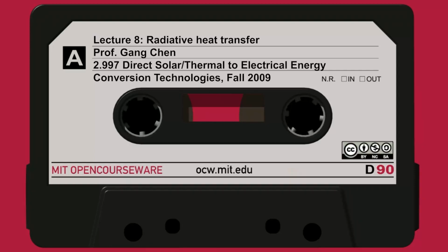So C equal to 1, and rather than doing a blackbody spectrum here, I was trying to do this by hand, and then later on I found that I still couldn't solve the equation, so I got the team again into my office. He has a code that calculates a few curves, you'll see later on. So here is the radiation from the sun, and I say absorption is 1 between 0 and lambda. So this is 1 times whatever comes from the sun: the view factor from sun to Earth surface, the surface area of the sun, the blackbody emission of the sun, d lambda. That's what comes to the Earth surface.